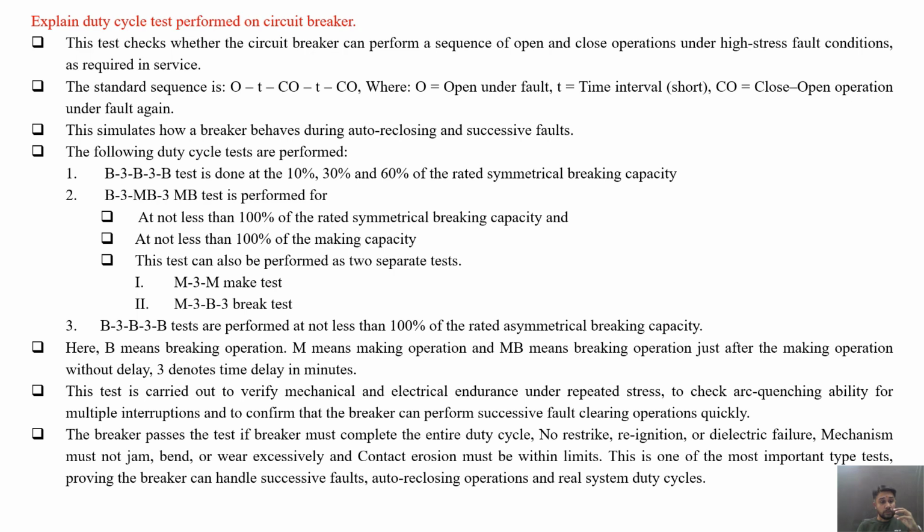Now, the breaker passes the test if the breaker completes the entire duty cycle, with no restrike, no reignition or dielectric failure. Mechanism must not jam during the operation, must not bend the contacts or wear excessively, and contact erosion must not occur, or if it occurs, it should be within the specified limit.